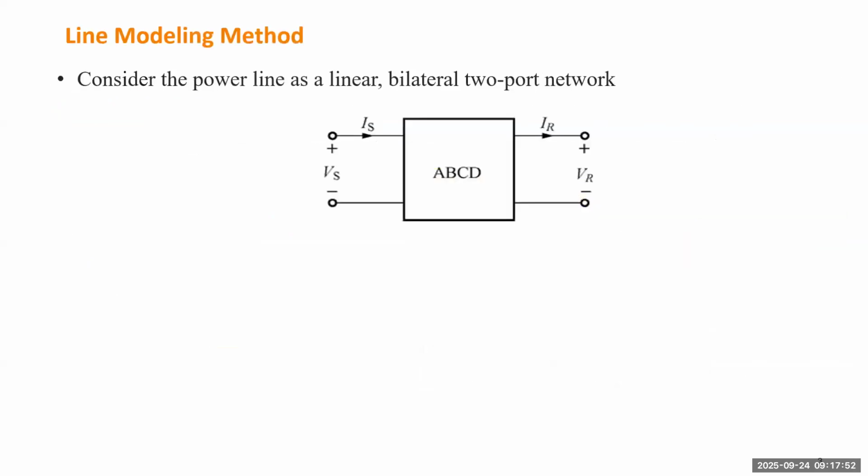The approach for every line model, as I explained on Monday, is to develop a transformation of the source voltage and source current as phasors to the line current and line voltage as phasors. And there will be only 4 parameters involved in the line. If the line is passive, those 4 parameters can be the 4 entries of a 2x2 matrix.